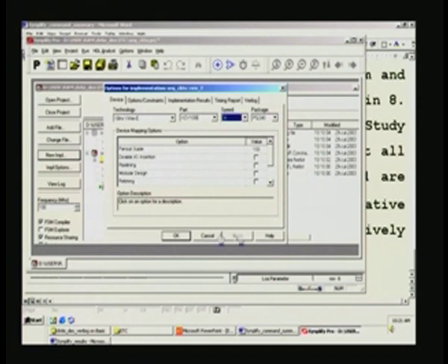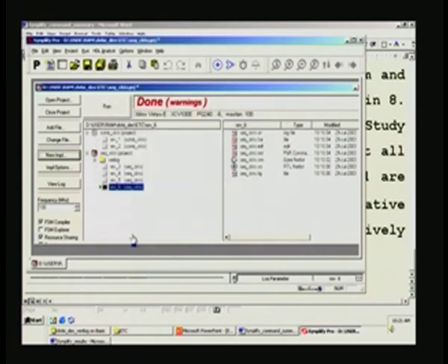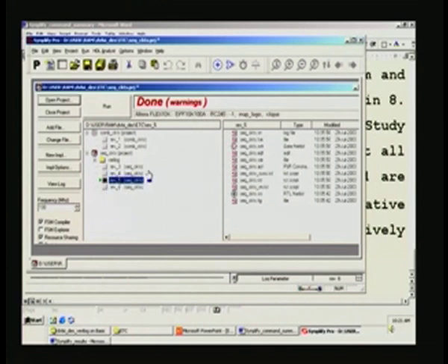So that is the motive there. And in addition to this, we would also like to compare with another vendor, more or less the same capacity, and I have done for another leading supplier for FPGAs, that is Altera. One of the popular series in Altera is the Flex 10K series, and the device selected is EPF10K100ARC240-1.